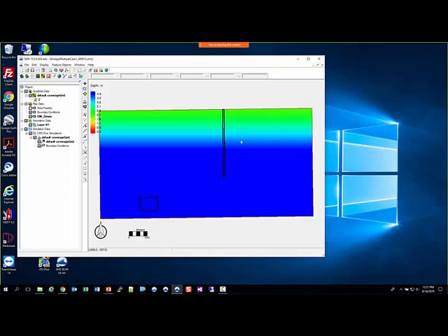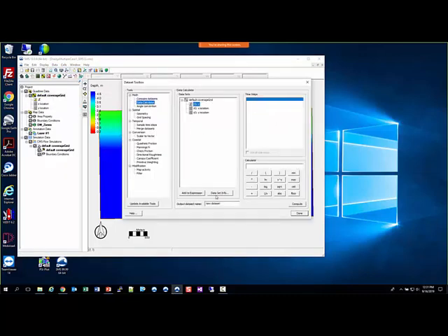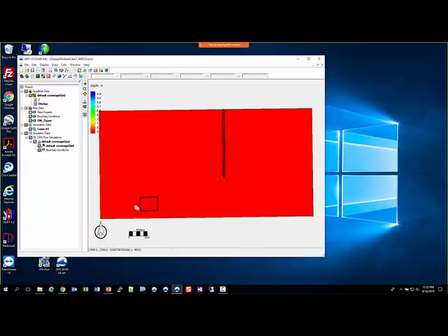So now let's use these polygons and select those cells. So the way we do that is we will select the first one. Actually, I'm getting a little bit ahead of myself. We need to create the different data sets for these two. So let's go to the quad tree, and then under Data Set Toolbox, there's a calculator. And so our first one we're going to do is just the dredge data set. And we're going to set a default value of -999, hit compute, then done. And you see it located over here on the left-hand side.